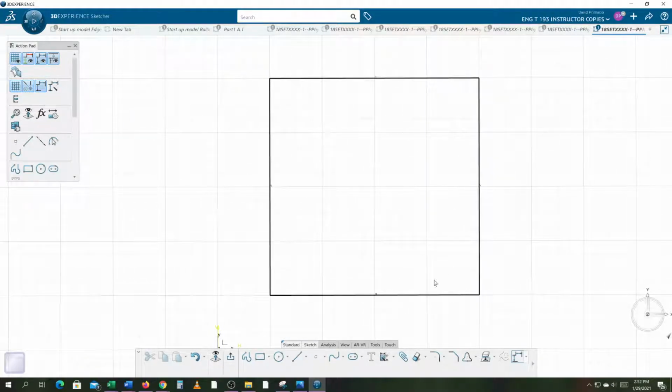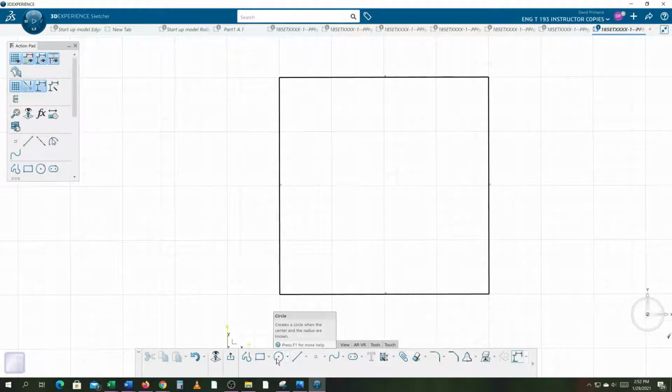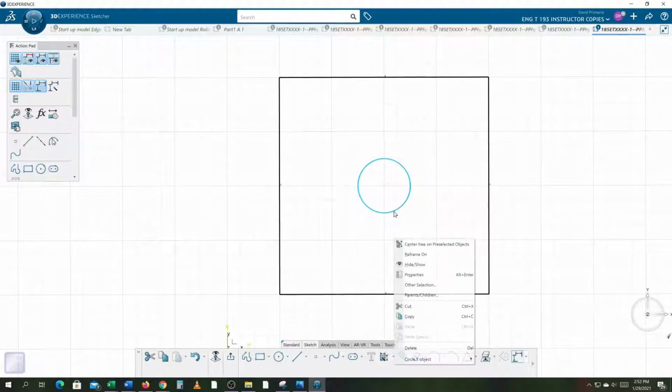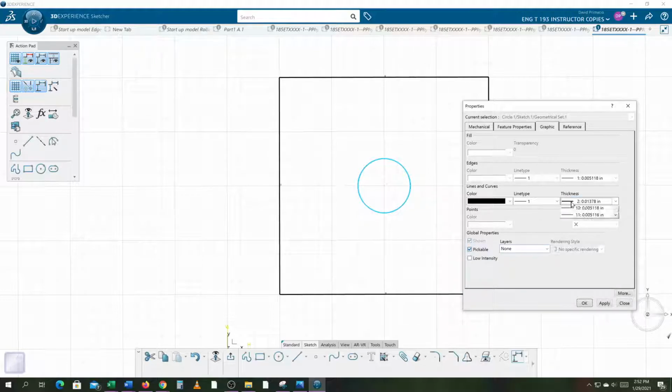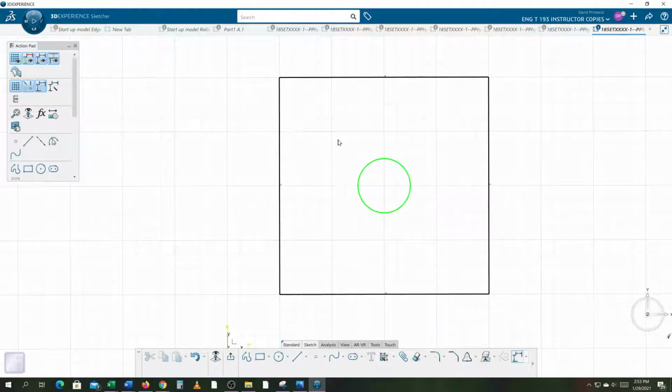So earlier we had created the pocket, but we didn't put the fillets in. And then this is a cutter that's going to be directly over the top of this pocket, if you will. Say we're 3/8 of an inch or 1/2 inch above the pocket before the operation started. I'll make this green. It's probably not the best color. Well, that's going to reference the cutter. Okay, and then we're going to come over here and cut it.